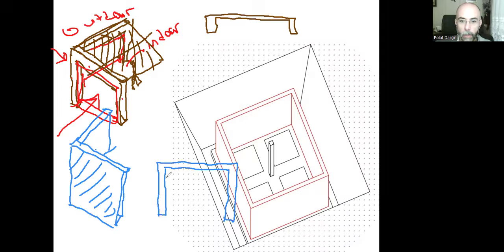And so all this surface will be load bearing and it's just one material. It's just reinforced concrete. There shouldn't be any lines like that. We shouldn't make a drawing like this. Okay, these are wrong because it's the same material. There shouldn't be any lines there.